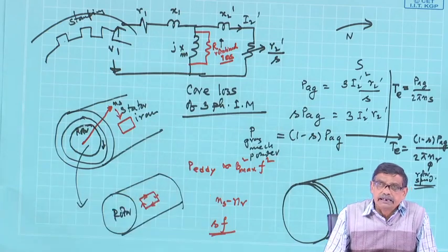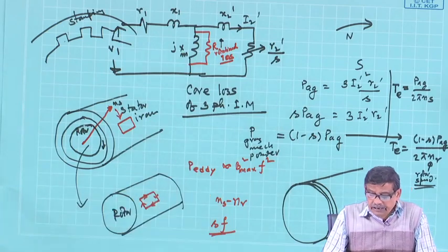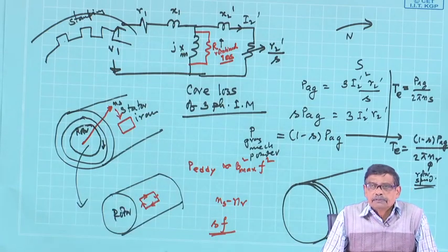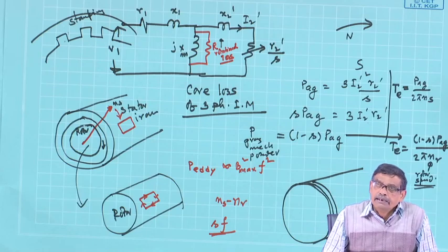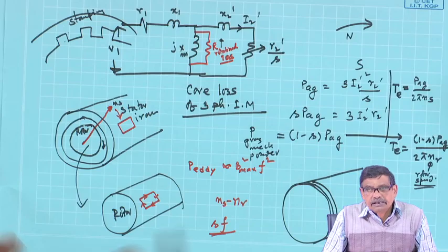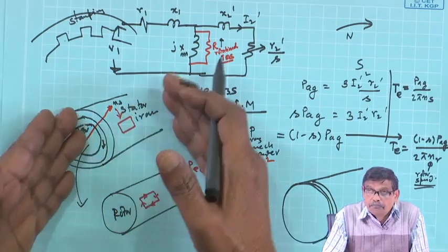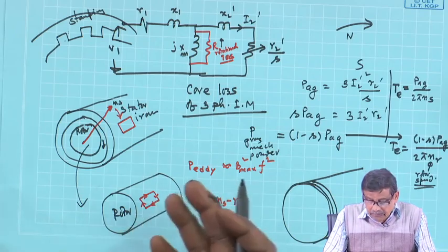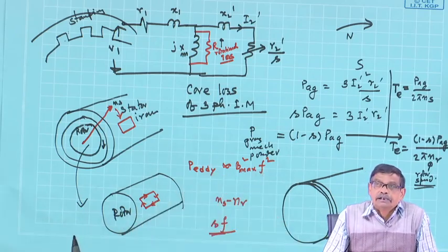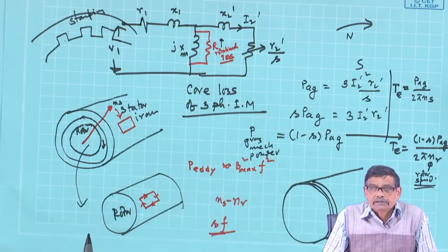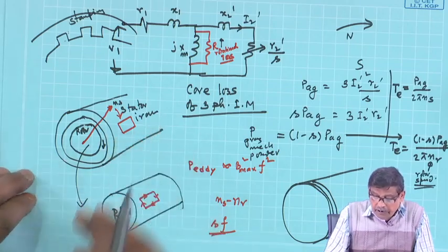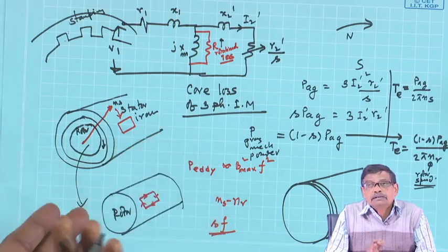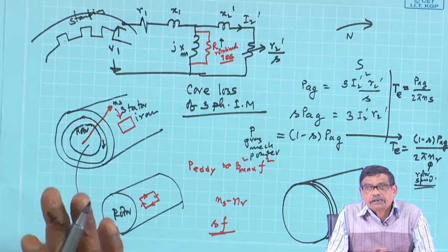So, you take care of that, try to reduce the rotational loss as far as practicable by using stampings while constructing the stator iron. It is not a solid block of iron. If you use solid block of iron, iron will become too heated up because of eddy current losses. Okay, so, always remember circular, thin, short slotted plates are used.